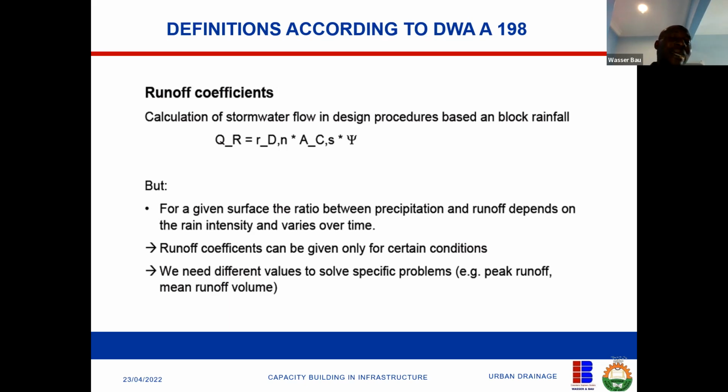There are charts and tables that are meant for that, and I'm going to give us one developed by the Federal Ministry of Works, Abuja. That's what we are using for now, because that one has been able to capture the rainfall intensity of every city in Nigeria. Then this symbol, I don't know what you call it in Greek, is the C, which is the coefficient of runoff. So this is the universal formula for every storm flow. It is the intensity of rain multiplied by the catchment area where the rain is falling, then multiplied by the runoff coefficient.